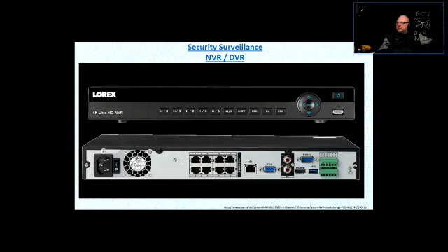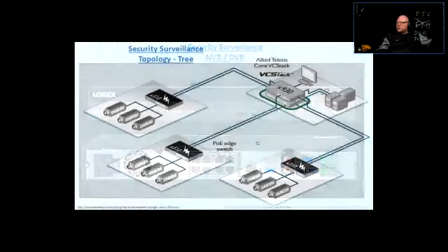Then that switch would be connected also to the network, and with all the IT programming of the network setup, this NVR is going to see that switch that is connected to the same network, and is going to grab the signal from the cameras that are connected to the switch. So a bunch of programming is involved, and this would be one of those situations.